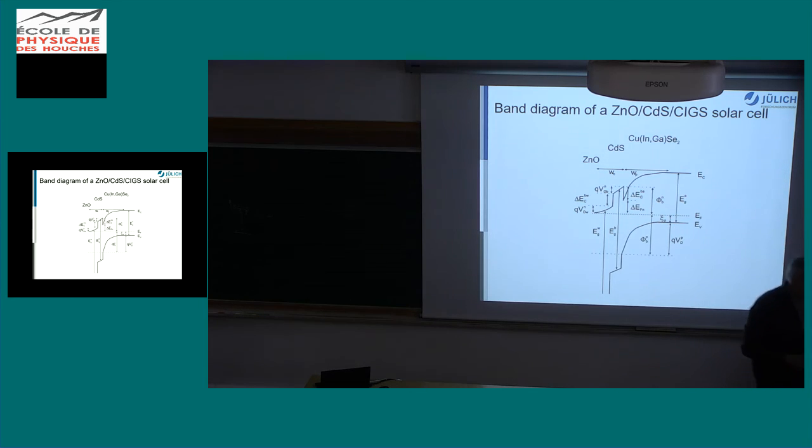So it's not really critical here. The interesting thing is, why do you need three layers? Say the zinc oxide is very highly doped, so it also has a large band gap energy. So it's transparent, and it's attracting electrons. So electrons go from here to there, hopefully hopping over that barrier, if there is really a barrier.